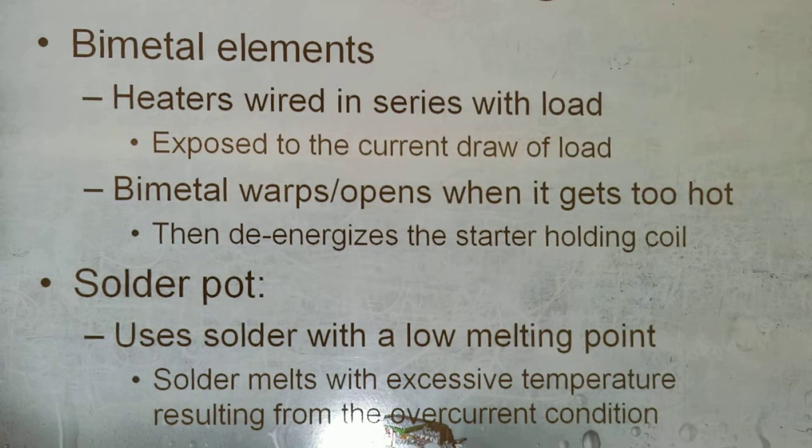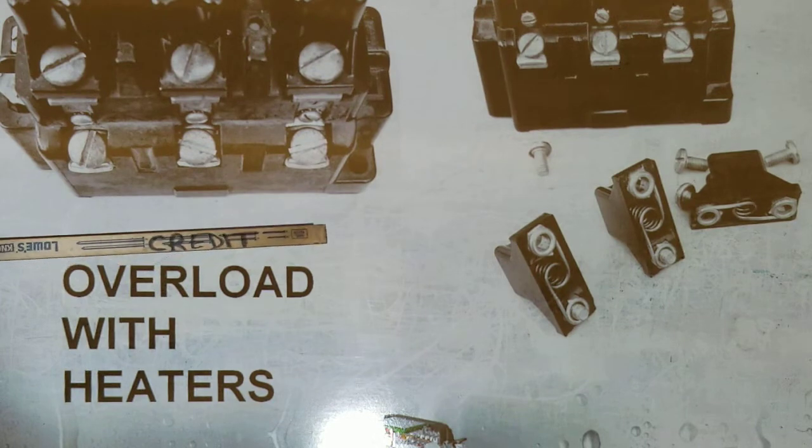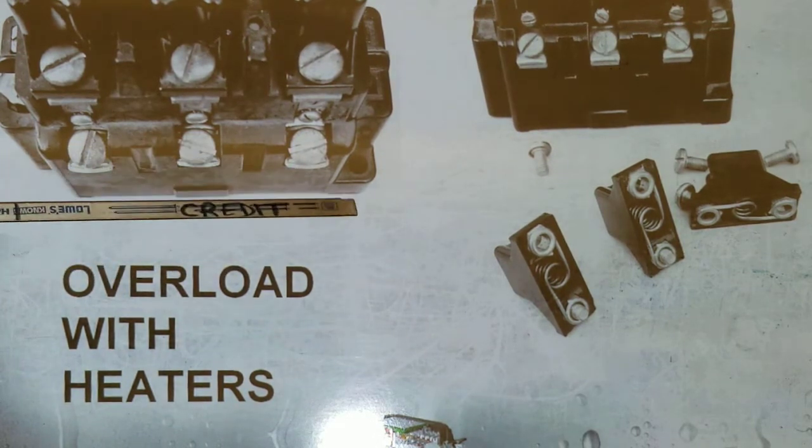Solder pot uses solder with low melting point, solder melts with excessive temperature resulting from the overcurrent condition. Okay, so the bimetal elements, the heaters, that's what they're talking about here.